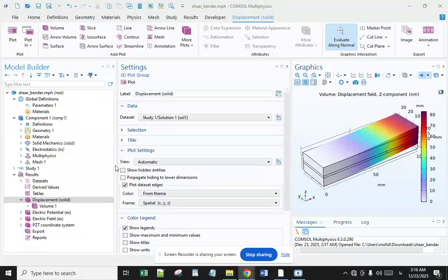Electrically, the electric potential was found to be quadratic for the extension actuation mechanism, piezoelectric phases, and linear for the shear actuation mechanism, piezoelectric core. Besides, the sandwich beam was supposed to be short-circuited. For example, electric potentials were imposed on upper and lower faces of piezoelectric layers, and natural boundary conditions, free charge, were assumed on the remaining lateral boundaries.